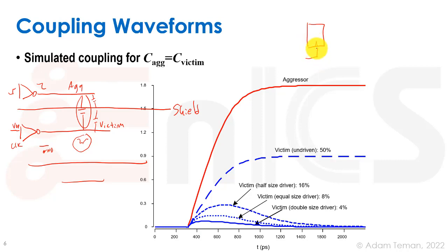that a flip-flop type of thing is an edge-triggered element. So when the clock rises, it samples the D over here and moves it over to Q over here. And if we get a glitch, that's going to cause another clock edge, and we really don't want that. Besides anything else, we don't want any noise to happen on the clock net. So our main reason for using shields, and that's why we do it extensively, is to protect the clock net.